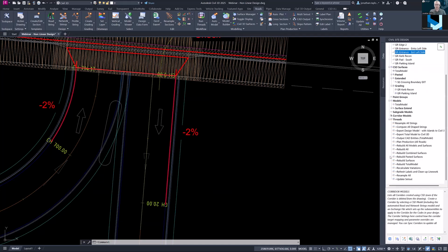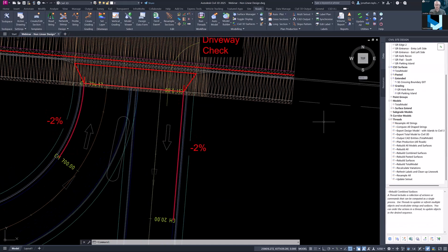In fact, just so you know, while I was building this and putting this together, if you want to quickly get CAD output or line work polylines in the drawing, head to tool space, and you can do this right now. Output CAD entities and just double click. That will generate for you polylines without you even having to go to CAD output. If you then head down and want to get rid of it again, refresh labels and clean up line work, double click.